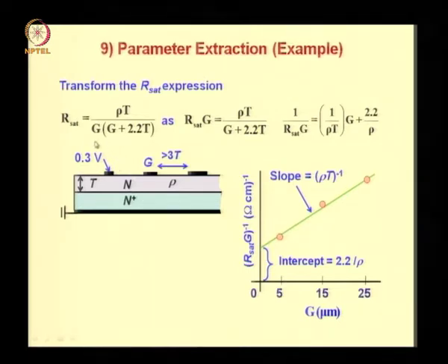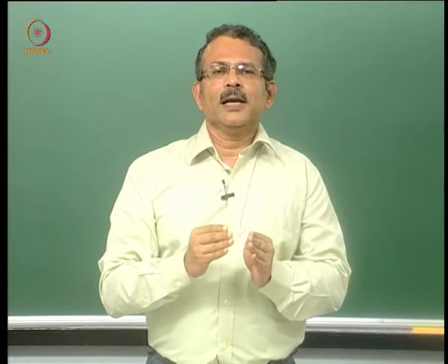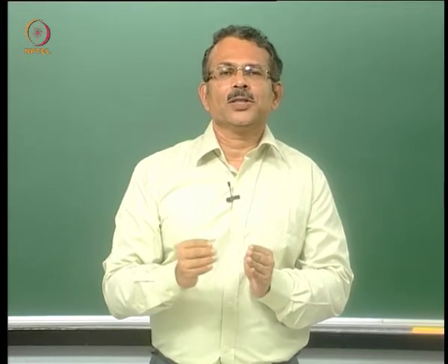To measure the resistance, you will use a small voltage, because if you use a large voltage you may have velocity saturation effects and so on, which are not included in the resistance expression. So our resistance assumes that the mobility is not varying with the applied voltage or field.